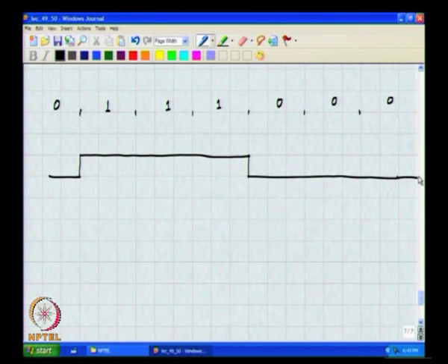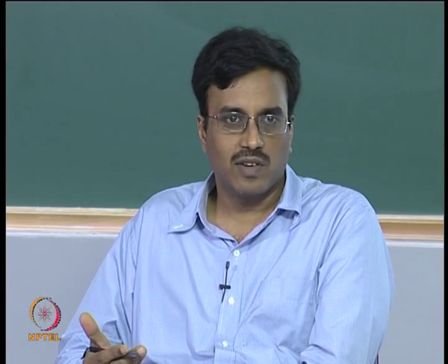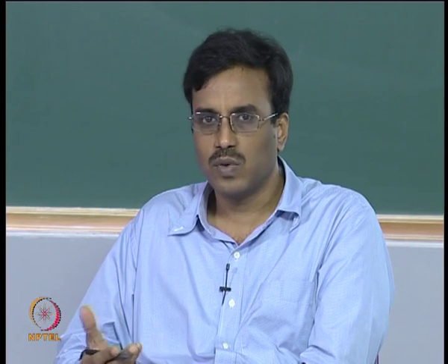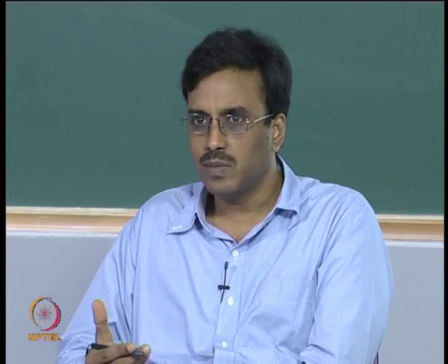All right. And now, the rise and fall times are, first of all, not 0, and second, they could be asymmetric. This is also a very common thing. For example, if you look at a CMOS inverter, if you do not size the devices properly, you will find that there is always a difference between the rise and fall times.